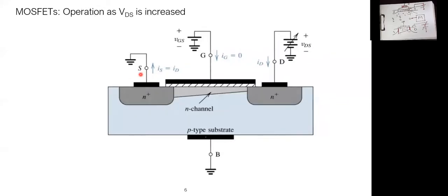What will happen is as follows. This is the reduced channel, or the ramped channel, due to having a higher voltage applied to the drain. As much as you increase the drain voltage, this point starts to reduce more and more, because it indicates a lower probability, that's right, to find an electron, because once the electron reaches this point, it will be directly attracted to the drain